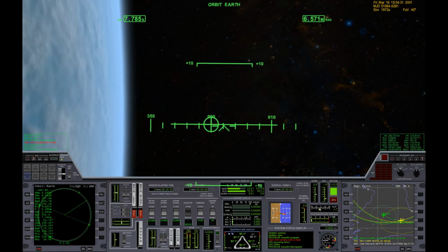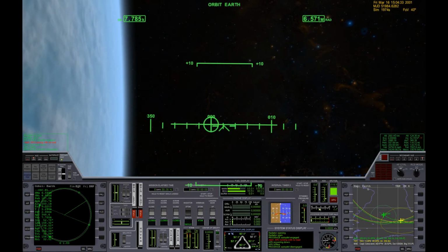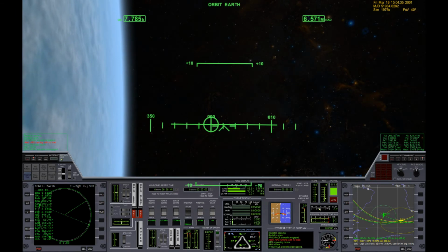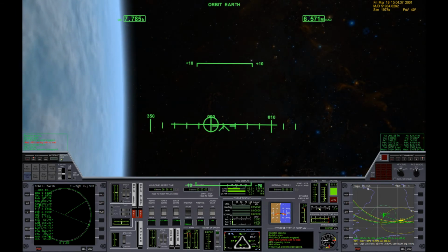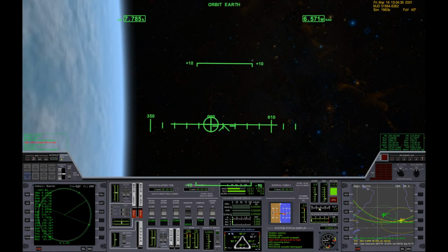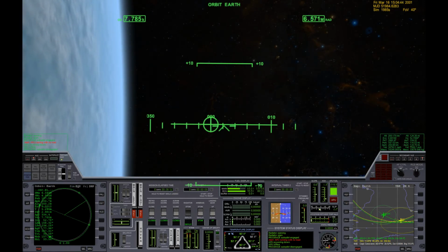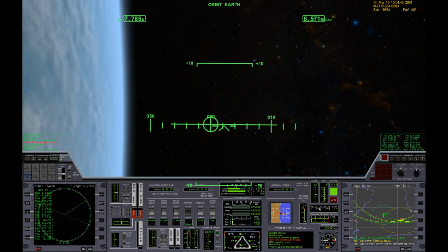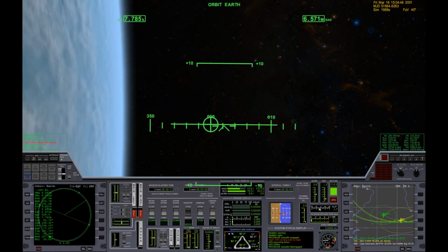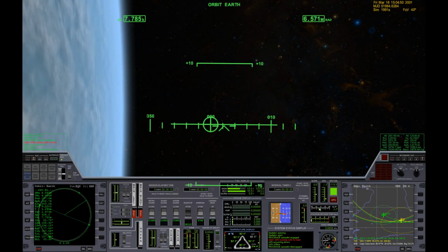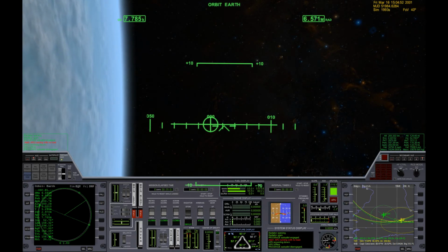So you have to really know what you're doing to the craft, because there's no sort of autopilot detected the temperatures are getting too high and is now pitching down to decrease the angle of attack and decrease the, or rather increase the vertical speed. No, it won't do that. You have to memorize that.